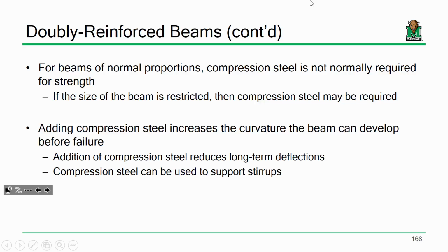In design modes, given a rectangular beam or a T-beam, we can design a beam, and we haven't really needed to account for steel in the compression region. So it's not necessary. However, it's also more often than not there anyways.